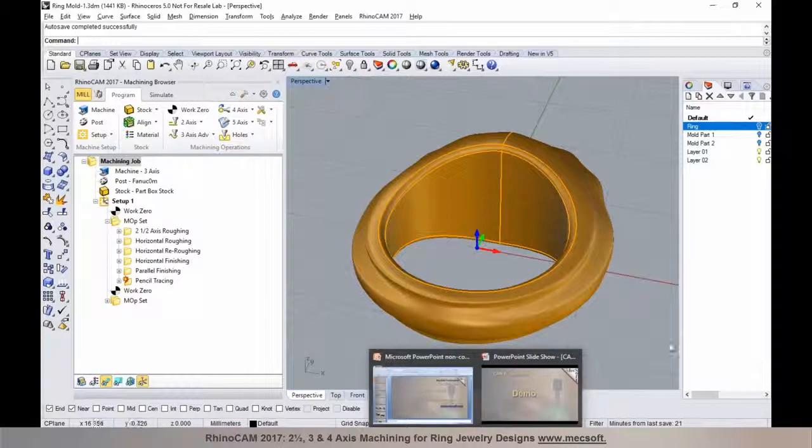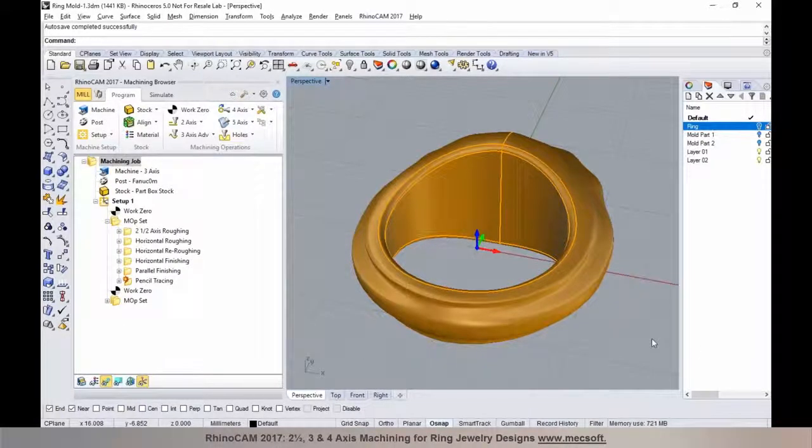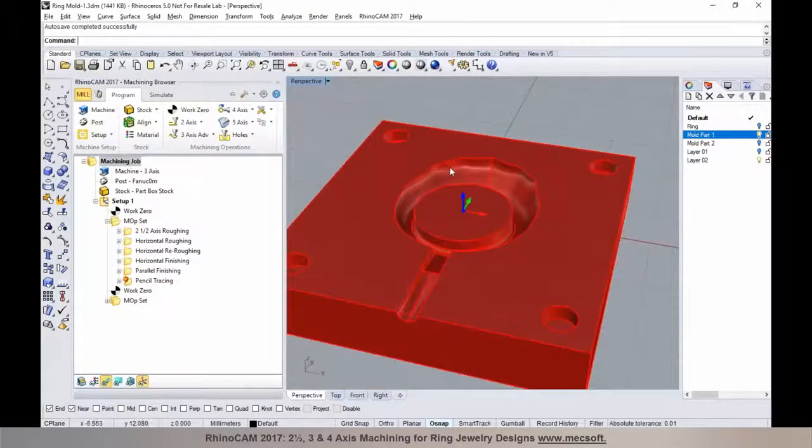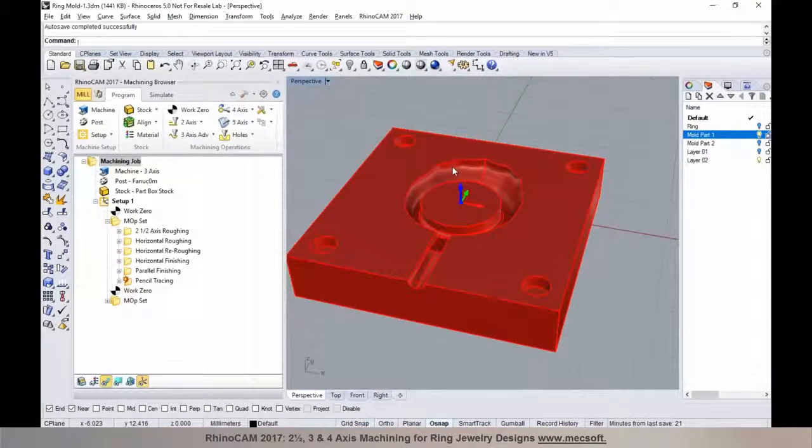Before that, I just want to interject a little bit here. Another word on process. So what they just did or showed us was the master mold for maybe a wax model. So you're creating an injection mold that you would create a wax model that we later take to an investment casting process.